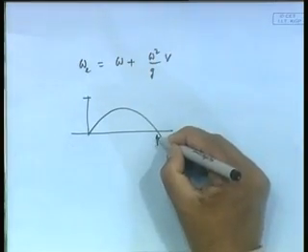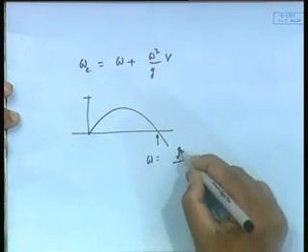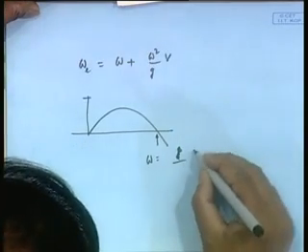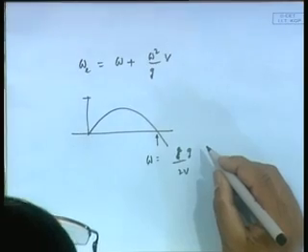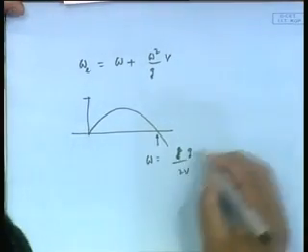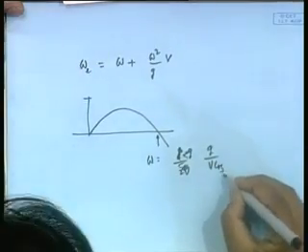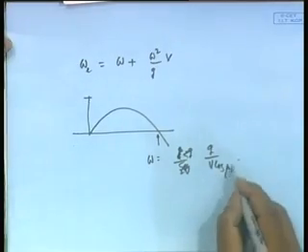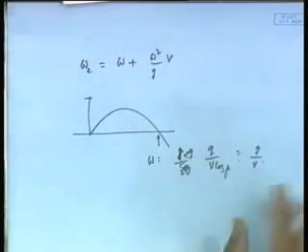Now we have found out also, let's put in a number. What was this omega? Let me just tell, because I want to spend a few minutes on this number here. This is G by 2V cos mu. Okay, this was G by V cos mu. Now see, just a simple thing. Say cos mu is equal to 1, so it is G by V in a following wave condition. What can be the possible number at which this occurs? That's very important, just physically understanding.